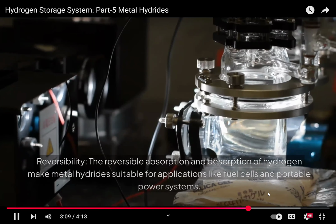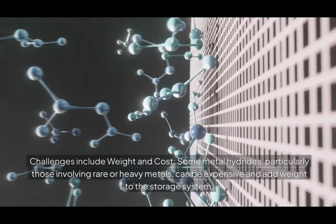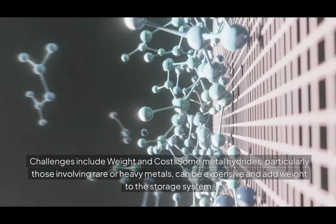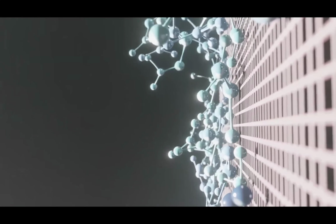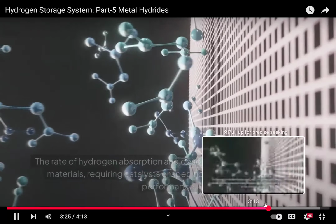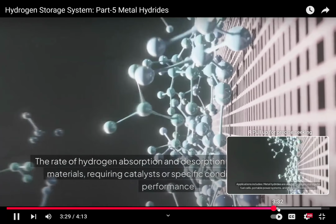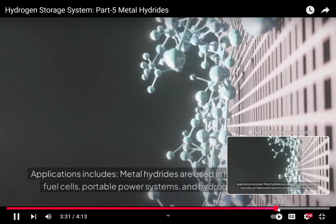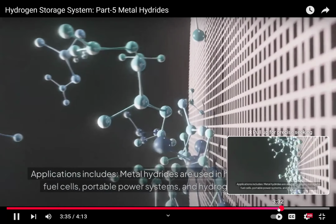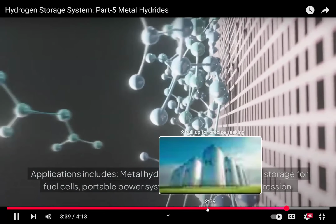Challenges include weight and cost. Some metal hydrides, particularly those involving rare or heavy metals, can be expensive and add weight to the storage system. The rate of hydrogen absorption and desorption can be slow in some materials, requiring catalysts or specific conditions to improve performance. Applications: metal hydrides are used in hydrogen storage for fuel cells, portable power systems, and hydrogen compression.